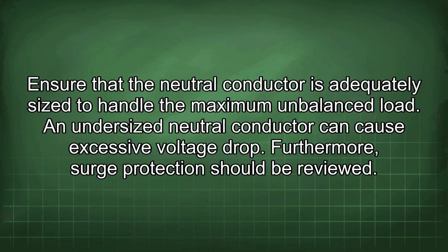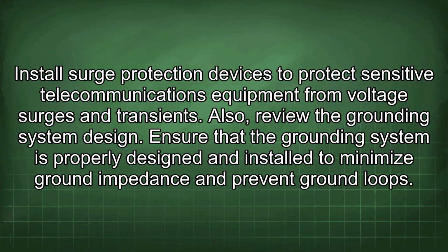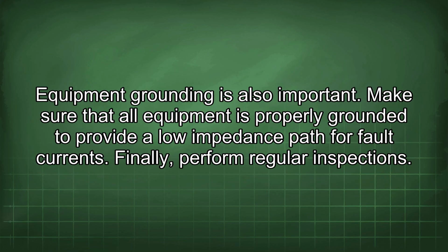Furthermore, surge protection should be reviewed. Install surge protection devices to protect sensitive telecommunications equipment from voltage surges and transients. Also, review the grounding system design. Ensure that the grounding system is properly designed and installed to minimize ground impedance and prevent ground loops. Equipment grounding is also important. Make sure that all equipment is properly grounded to provide a low impedance path for fault currents.